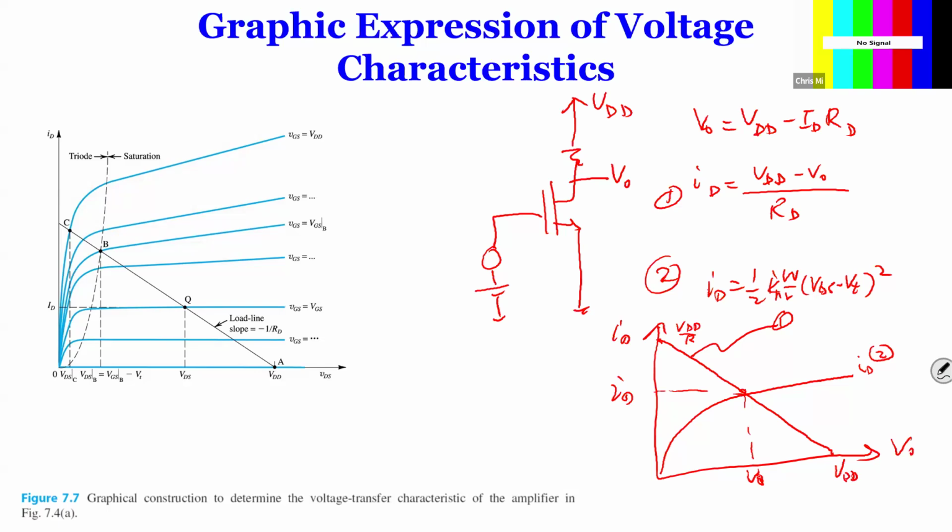And here is where you enter the triode mode, so you want to avoid this range. That's your lower limit, your minimum output. And then here is your maximum output. So between these two is your output range. The Q point is supposed to be your bias point, the DC biasing point. The Q is your DC biasing point.